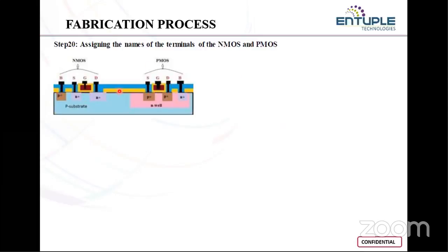Okay, so now when you move into layout, you have different types of layers, right? It depends on the technology, or the particular fabrication unit. Certain fabrication units don't have any order in which you need to get the layers, but certain fabrication units have a specific order, like first you need to place the substrate, then you place the oxide, then you go for metal, or you start with contact. So they have an order in which you have to create the layers.